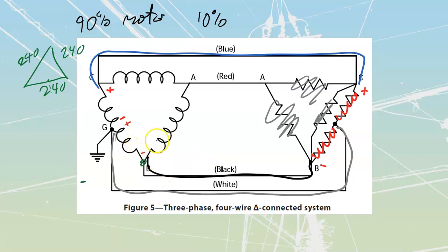I'm going to be able to deliver current from my negative. Let me just change the color marker over here. We're going to go to green. I'm going to deliver current along through here. That current is going to go and travel through my load from negative to positive. And if it's only that side that's operating, I can then take that current all the way back through to here, and it can circulate through that winding and come back out.